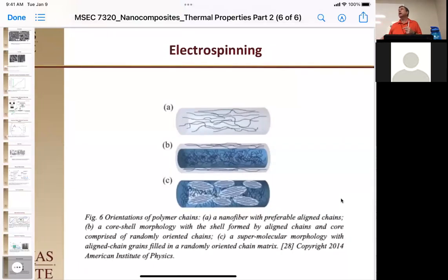Most of the fibers you get out of this are submicron, in the nanometer range. You can get fibers down to 50 nanometers, 10 nanometers using this method. It's a very easy method to get polymers down to that size, other than the safety interlocks and stuff. Most of the time it's done in solution, but you can do it in melt.